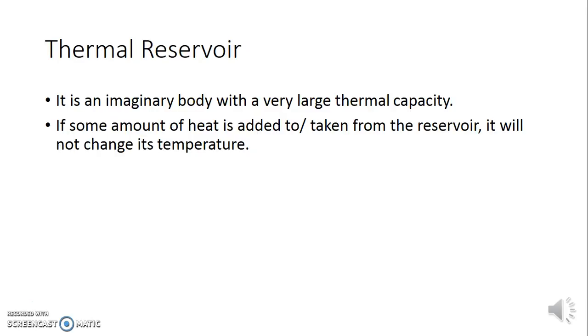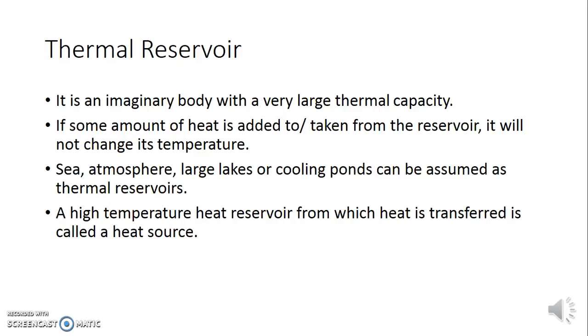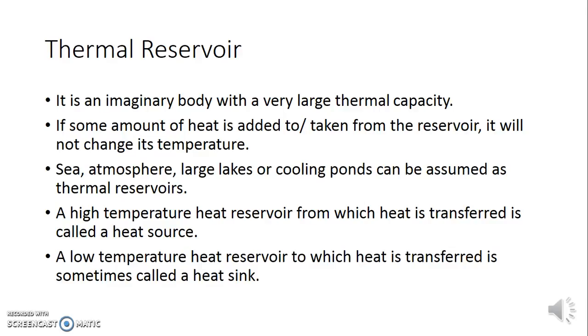Thermal reservoir or heat reservoir. It is an imaginary body with a very large thermal capacity. If some amount of heat is added to or taken from the reservoir, it will not change its temperature. Sea, atmosphere, large lakes or cooling ponds can be assumed as thermal reservoirs. A high temperature heat reservoir from which heat is transferred is called a heat source. A low temperature heat reservoir to which heat is transferred is sometimes called a heat sink.